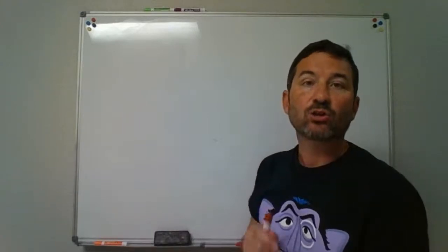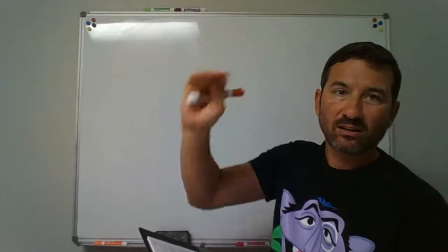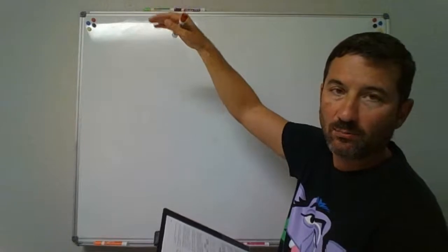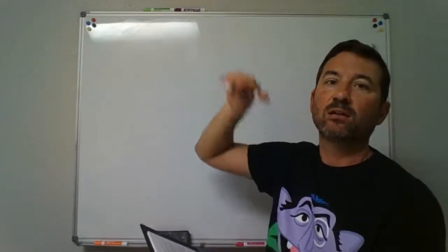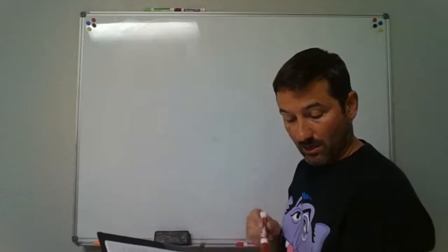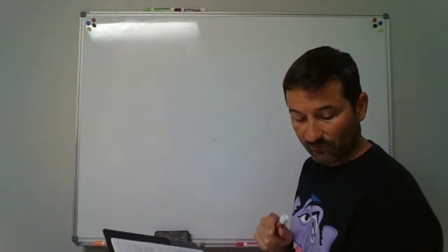Okay? But you begin counting them from the top floor and going down. You don't start at floor 1, 2, 3 and go up. It's going to say every 10, but start at the top and work your way down, with a relief vent at each 10th interval installed, beginning with the top floor.